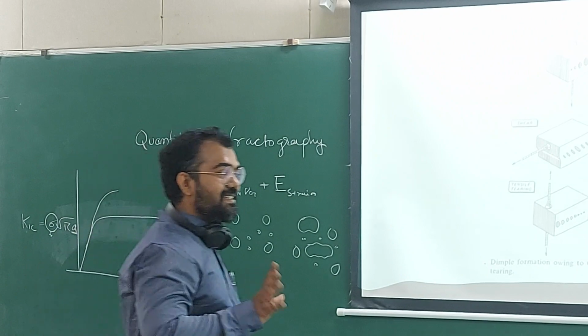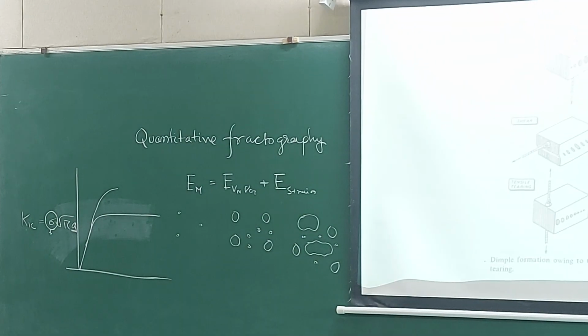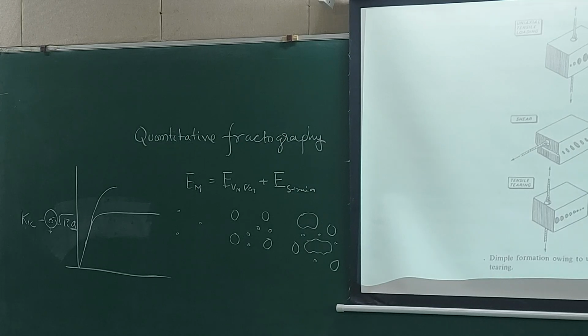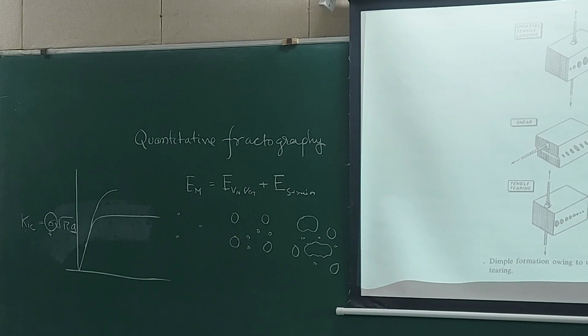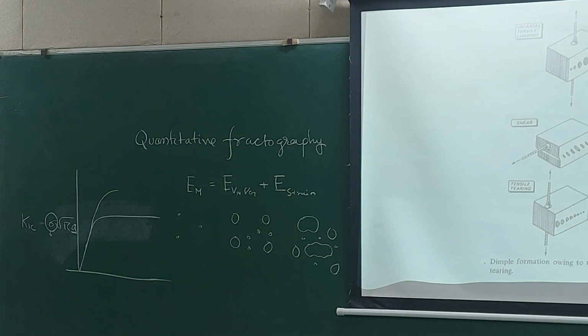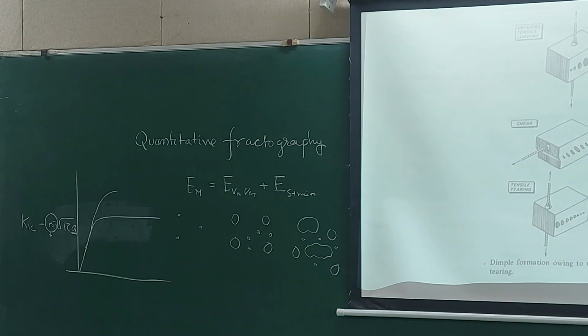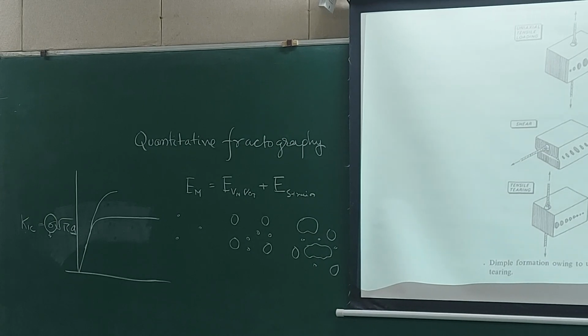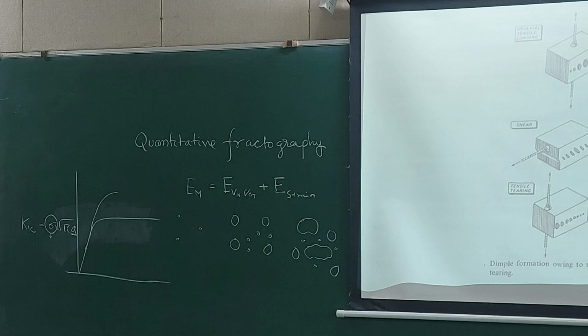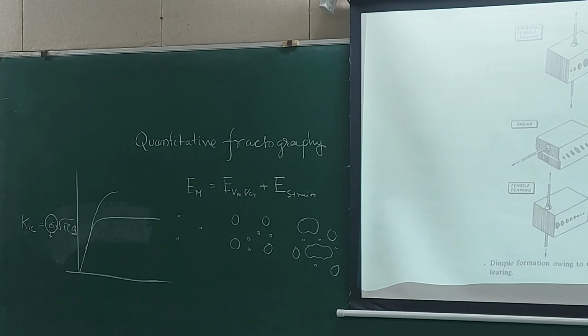But the kinetics is very different. If you have more nucleation happening, then it may happen that not all of them will grow to a larger size. Sir, is there any factor of time here, because if strain is more, then it will take more time to deform? Well, we don't say anything in terms of time, because we are not talking about time dependent deformation. In this case, kinetics is in terms of plastic strain. Plastic strain develops with time only, but we are not saying time because then it will make it time dependent.